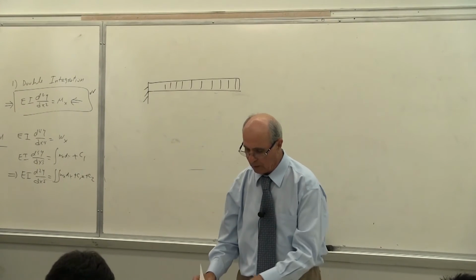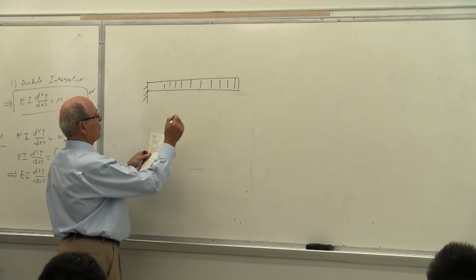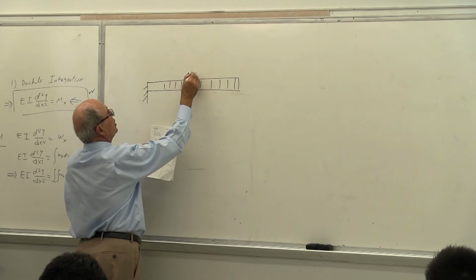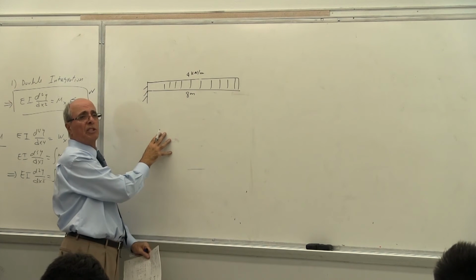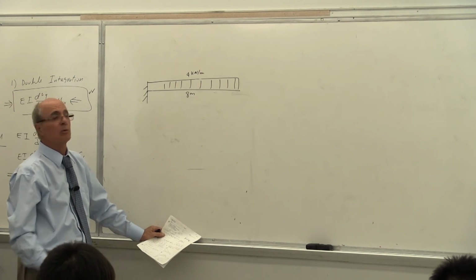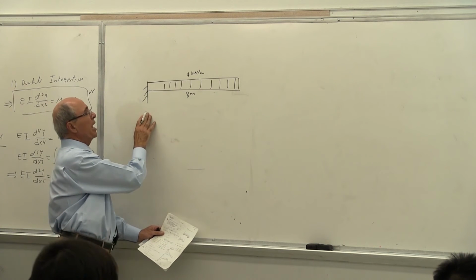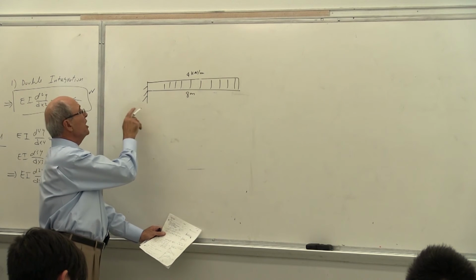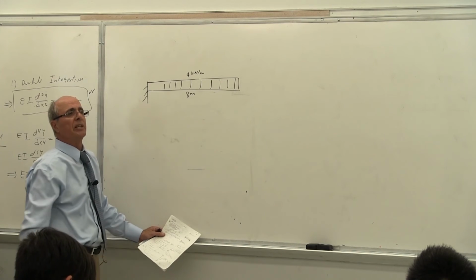This is really the bulk of the matter, and this has been a quiz in the past, so let's look at it this way. So we have here the length of 8 meters. The load is 4 kilonewton per meter. And if I give it like this to you, notice what happened there. This side is going to go down, yes or no? I already solved a problem similar to that. It was a triangle load, which was much more difficult, yes or no? But we have here a reaction and MA, yes or no? That system was indeterminate because I have AX, AY, and MA, 3 unknowns, 3 equations, yes or no?